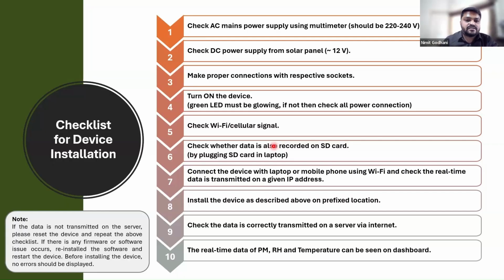Temperature will follow a regular diurnal cycle, and that will be the same for whatever we are using. Okay, so how often do we need to recalibrate a sensor? Earlier I showed some sensors that we put for a longer period at our calibration sites. Those sensors are calibrated for each and every season. So in India, we use summer, winter, monsoon, and post-monsoon seasons.